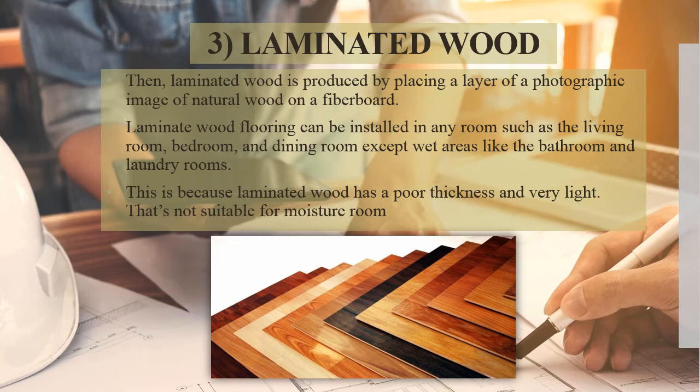Then there is laminate wood. Laminate wood is produced by placing a layer of a photographic image of natural wood on a fiber board. Laminate wood flooring can be installed in any room, such as the living room, bedroom, and dining room, except wet areas like the bathroom and laundry room. This is because laminate wood has poor thickness and is very light. It is not suitable for moist rooms.